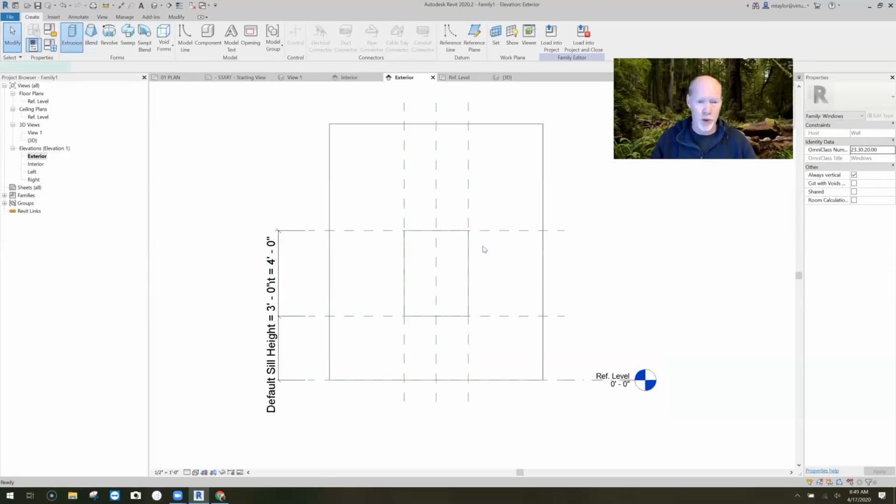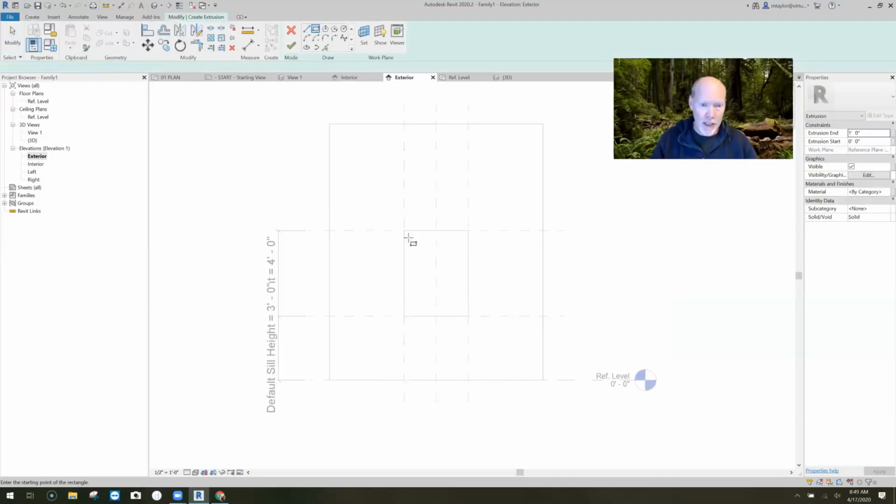So I'm going to build an extrusion. And I'm just going to click on rectangle. Let me use these two corners, okay? And then I'm going to say offset. And let's just say we want to offset 2 inches. And I'm going to come down here and over there and there and there. And I'm hitting TR on the keyboard for trim so I can get to trimming those. Oops, bad move, Mike. Trim that to that and that to that.